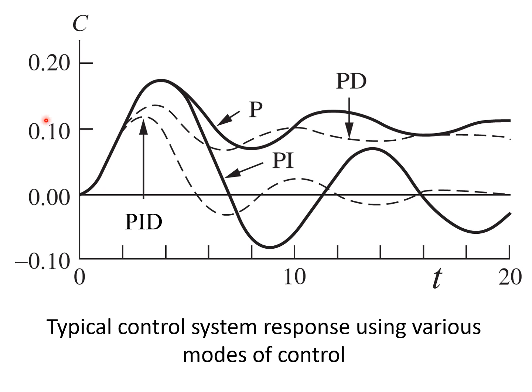Okay, for simple qualitative criteria for different controllers, this is the sort of response that we will get if we have a P controller. We'll get a response with an offset here. Same thing with the PD controller: we'll get less overshoot but with an offset. If we use a PI controller, we will get more oscillation, but at the end of the day, there will be no offset. If we use a PID controller, we get less overshoot, slight oscillation and no offset.